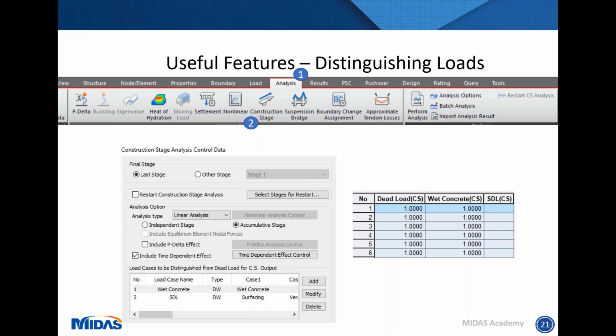When you come to doing your load combinations to Eurocode, concrete and steel have two different load factors, and as a result of this, being able to distinguish, at least in my case here, I chose to keep the wet concrete load case activated throughout my analysis, and the wet concrete load was also used to represent the weight for the concrete within the structure, and to be able to manipulate those two effects, one for the steel and one for the concrete,